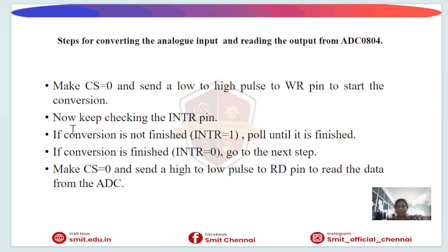An example conversion: if the reference voltage is 5 volt and the input voltage is 2.5 volt, what is the digital output? It is 2.5 divided by 5, multiplied by 255. What does 255 mean? We have values from 0 to 255, that is eight 0s to eight 1s, and eight 1s is 255. So we get an approximate value of 128.